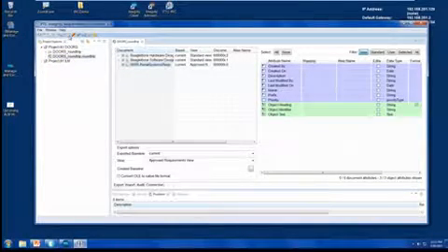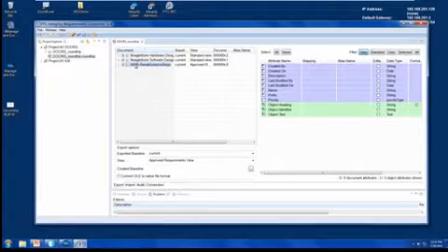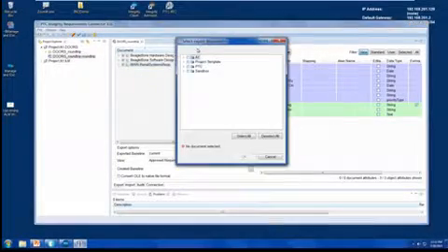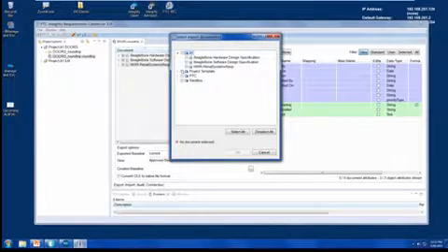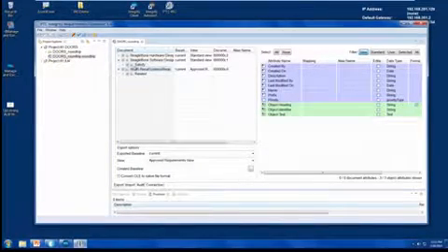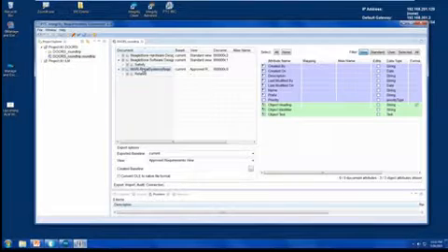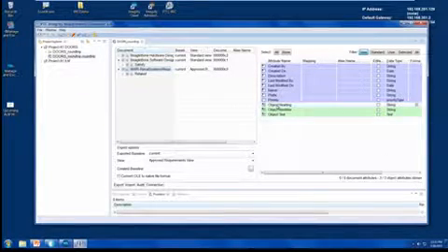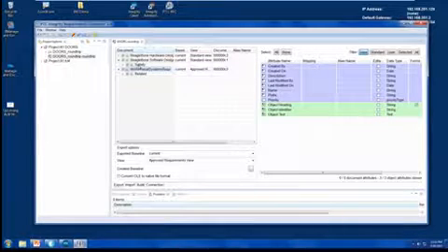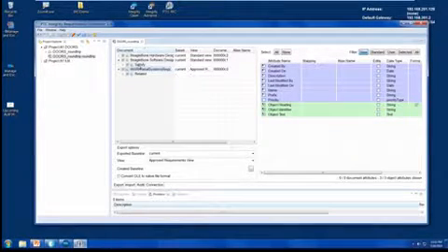To do that, all I need to do is add whatever documents exist in my DOORS database into IRC, and point them together. I've already got that. If I open up the twisty, I'll see the information that I'm going to be pulling out: the object heading, the object identifier, and the text, as well as the link information that was pre-existing in DOORS.